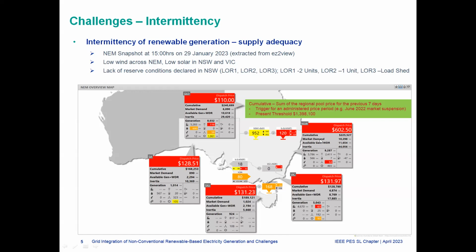It shows the generation available in New South Wales and also the inertia in New South Wales, which contributes about 44,000 megawatt seconds. Then it also shows the generation split. There is about 5,700 of coal, 566 megawatts of hydro, gas, then no hydro at the time.